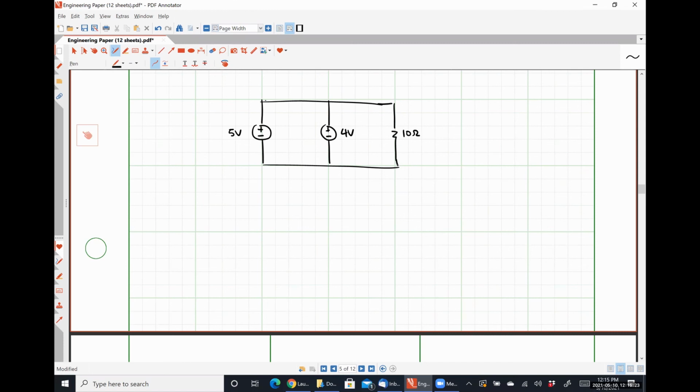So the AC problem is going to be a similar thing. It's just going to be a sinusoidally varying large short circuit current flowing through your system if you tried to wire them up in parallel. So for AC systems, you have to be even more careful because you could have the same magnitude, but different phases will still screw things up, right?